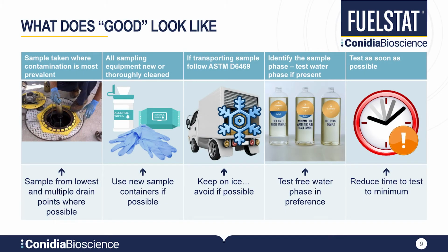Well, in simple terms, when taking a sample, it's important that the sample is taken from the lowest point of the tank, as that's where the water likely is going to be settled and organisms will be concentrated. Sampling equipment should be cleaned thoroughly. If transported offsite, the sample should be packaged on ice to minimize the chance of organisms multiplying or even degrading.